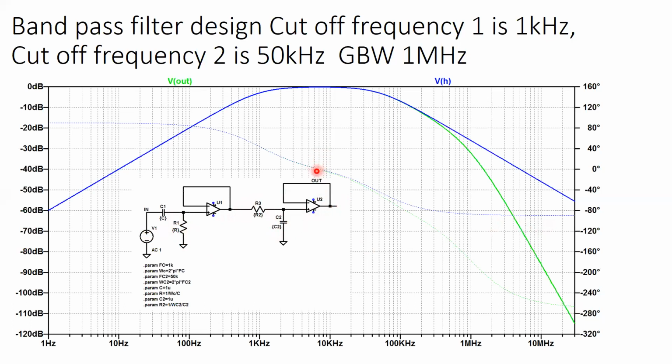At the band, it's actually zero phase. And out here, it's actually at minus 90, right? And these op amps add two more minus 90s. That's a way you can kind of estimate how many poles there are. It's not a perfect estimate, but take the phase and divide it by 90, and that's kind of how many poles you'll have. It gives you an idea.